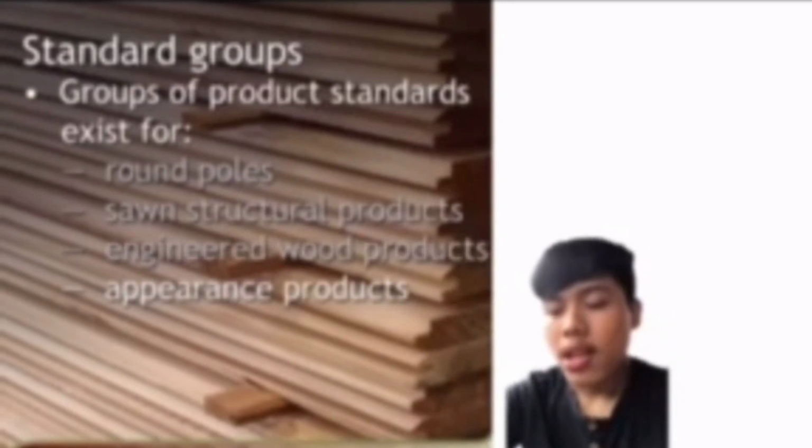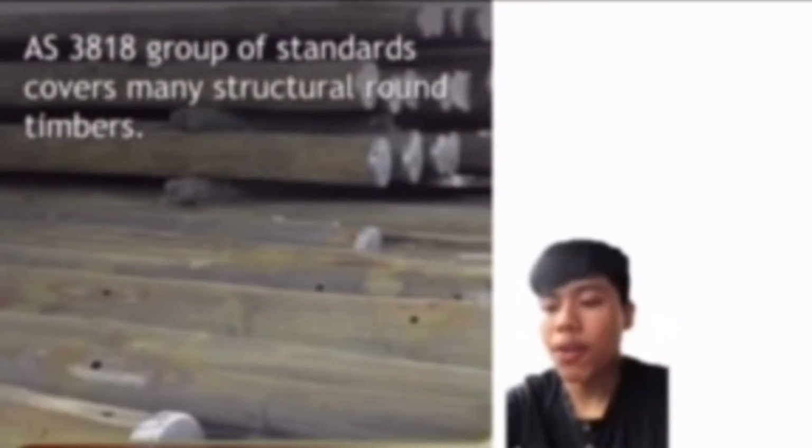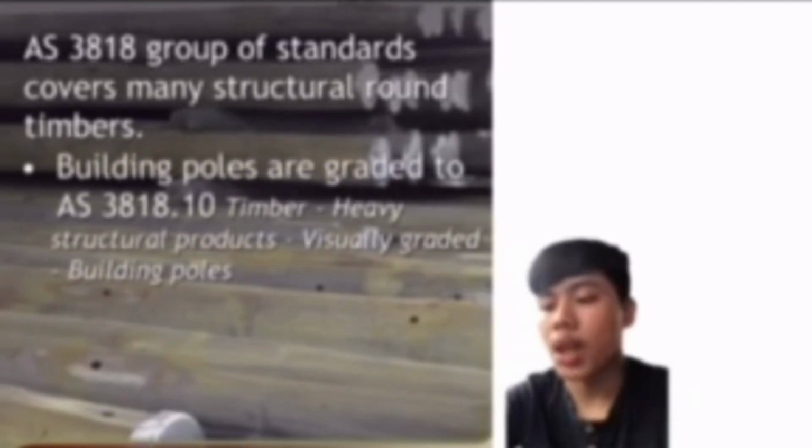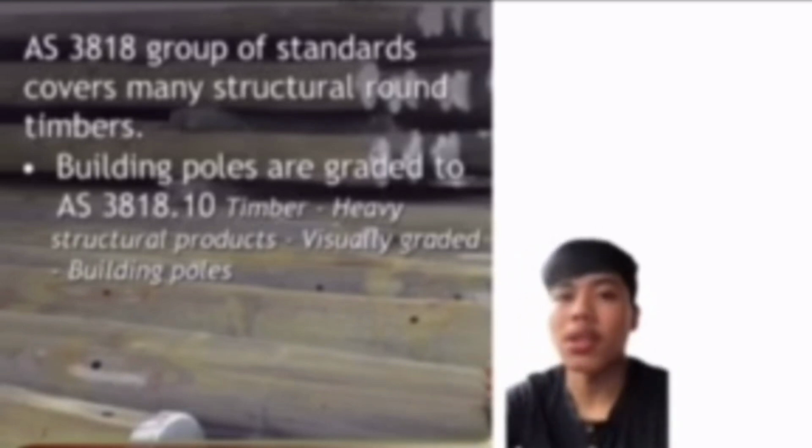The Australian Standard 3818 group of standards covers many of the applications for structural round timber. For example, building poles are graded to AS 3818.10, timber heavy structural products, visually graded building poles.